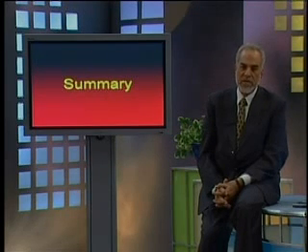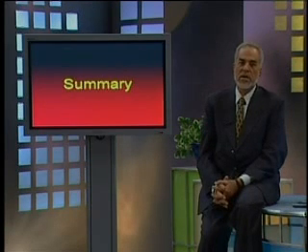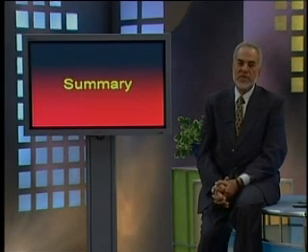We said in particular 2's complement for binary numbers, or the Radix complement, is quite a convenient representation and is frequently used for crunching these numbers. Then we just discussed how to add up two numbers without sign, unsigned numbers. We discussed half adder and full adder.